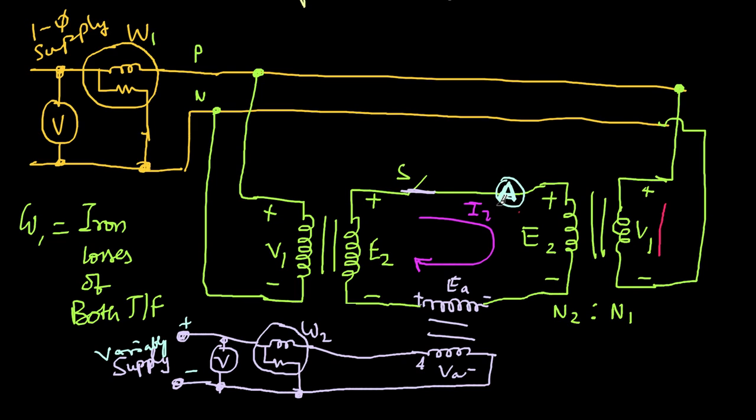Why? Because whenever current enters the positive terminal, that means this is consuming the power. So on this side the power will be released. So power will go like this. This is the arrow. So I am drawing the path of the I1 current, which is again the full load. And this I1 current will go down here. Now you notice this I1 current is entering into the positive terminal. That means the power is being consumed by this transformer, and the I1 current will leave like this, and then through the negative terminal, the I1 current will keep on going. So let me just add these two.